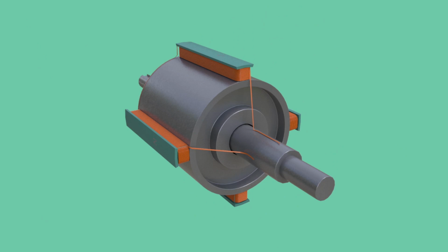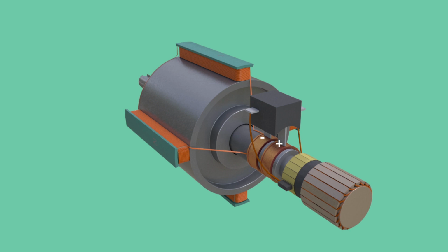DC current is supplied to rotor via a pair of slip rings. This is the reason why rotating magnetic field approach is used in alternator. If rotating coil method were used, slip rings would have to be fitted along with the armature coils in order to collect electricity. But transferring such high voltage electricity via slip ring is rather impractical. It is quite possible to transfer low voltage DC excitation current via slip rings.